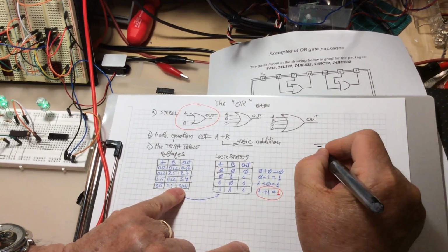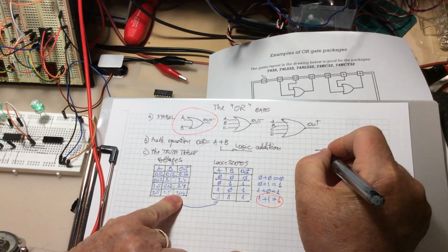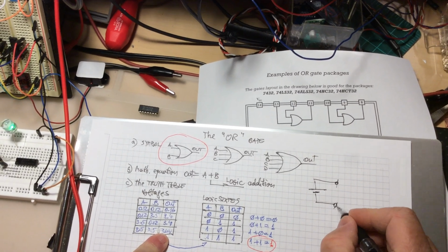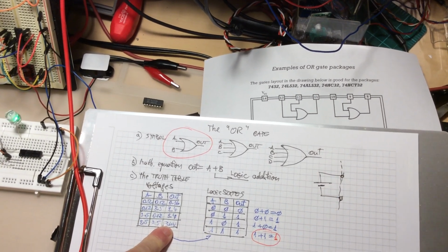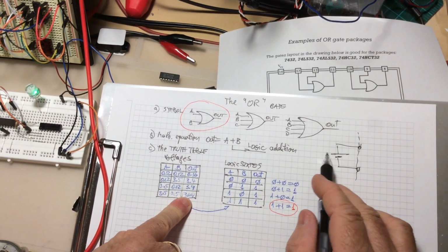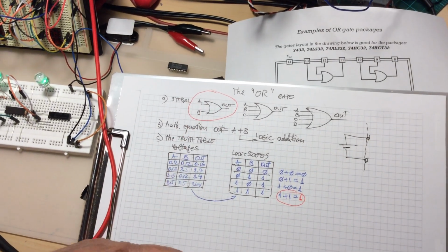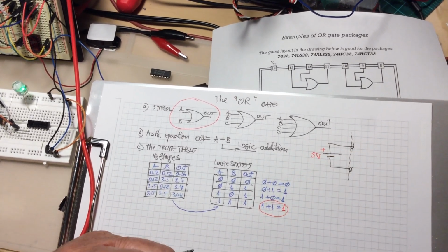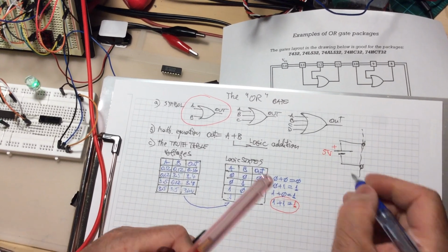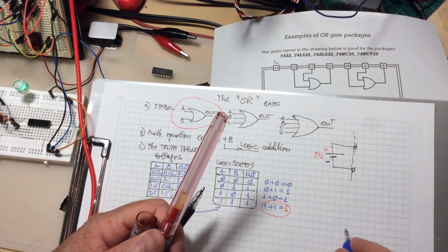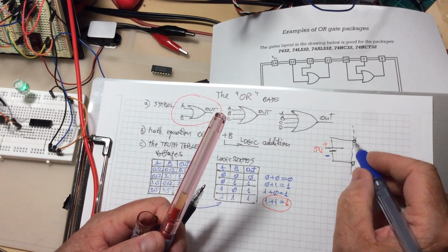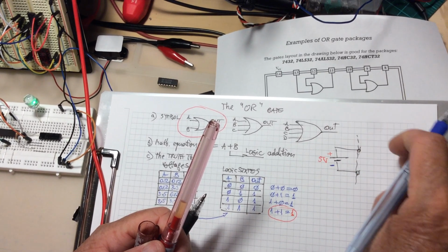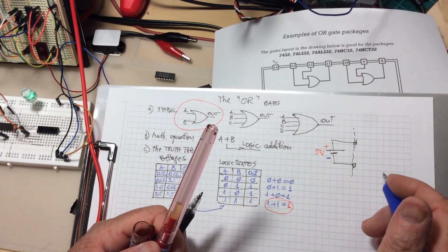This is how we draw an electronic diagram. Okay? Here I draw just a battery. The symbol for a battery is a long line, which is the positive. Let's say in our situation it is 5 volt. And the shorter one is the negative. So whatever you connect across these 2 points is the load consuming current or energy from the battery or the power supply.